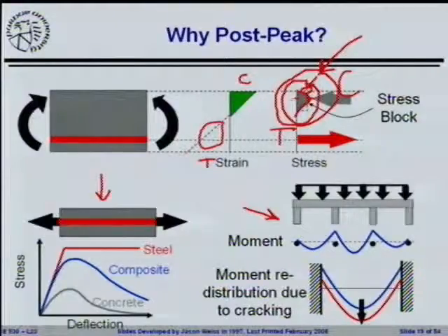I would dare say that while it was incredibly important for Whitney to do that in 1902, many of us have things sitting on our desk right now that would enable us to use this entire stress-strain response to design a beam. Because we could actually input an entire stress-strain response and use that directly without the Whitney stress block right now. It's just, is it worth the time and effort to do that? And that's a question that people have to decide and answer.